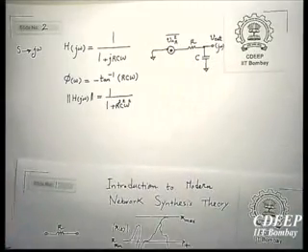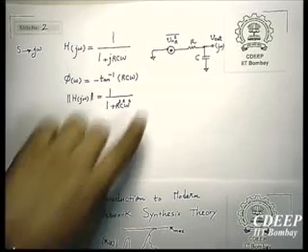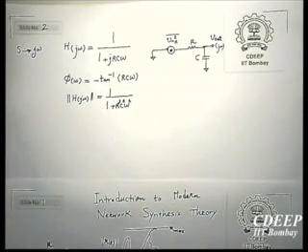So then here, this noise source has a flat power spectral density. However, filter is not flat. Therefore, output voltage of this system now will have a non-white spectrum. So, in other words, power spectral density is not constant across all frequencies, and it reduces as I increase frequency.